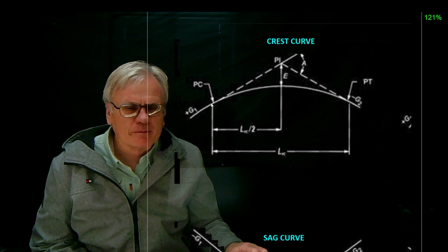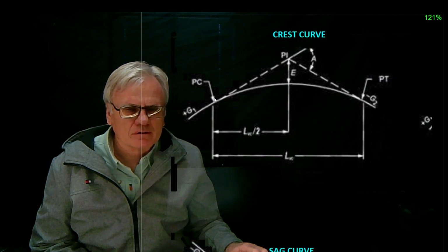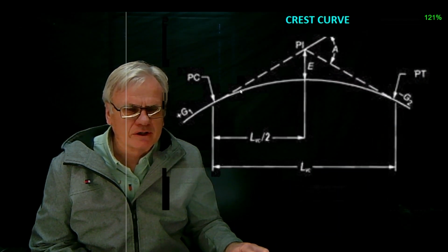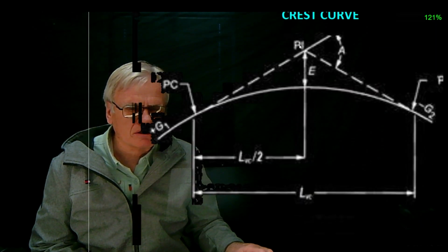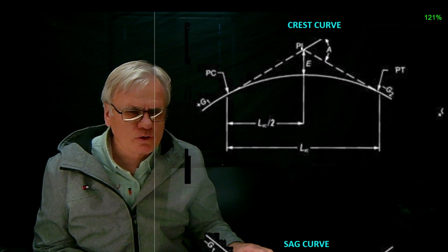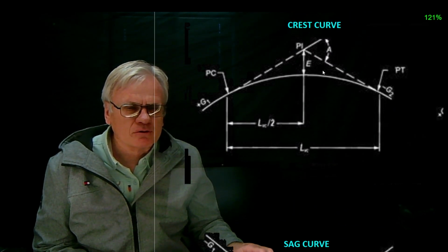when we deviate from it, we'll call that the point of curvature. Quite often, if we're doing this in the notebook, we might put a V in front of that, so vertical point of curvature is where the curve begins off of the tangent line. Likewise, if we look at this other tangent line that's going backwards, where the two tangent lines intersect, that's the PI, or point of intersection. This is just like we learned with horizontal curves, but we might put a V there, VPI, to remind us that it's a vertical curve.